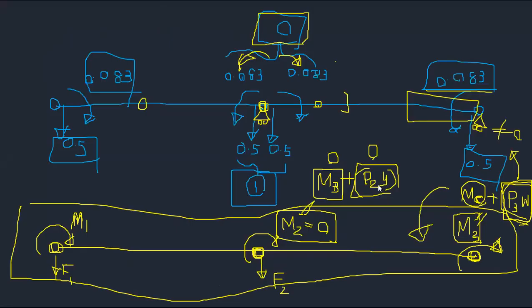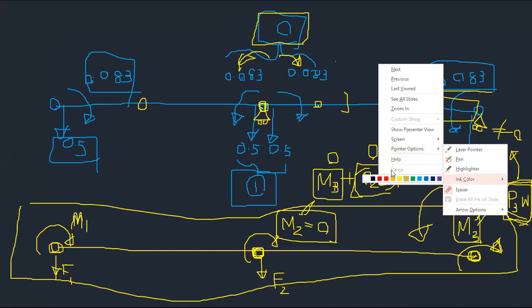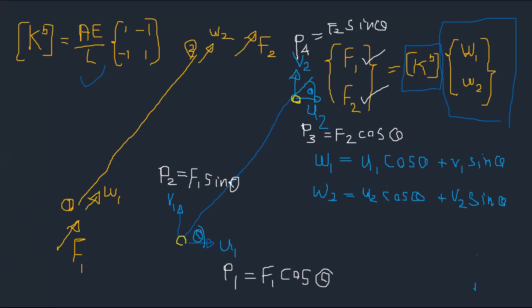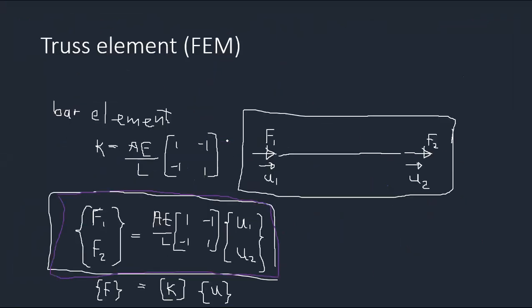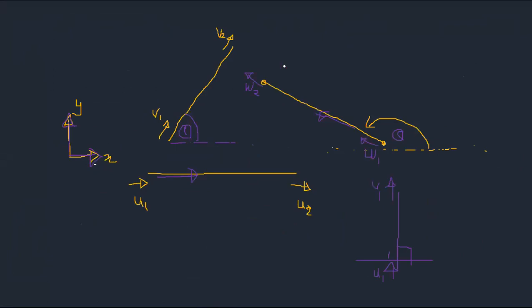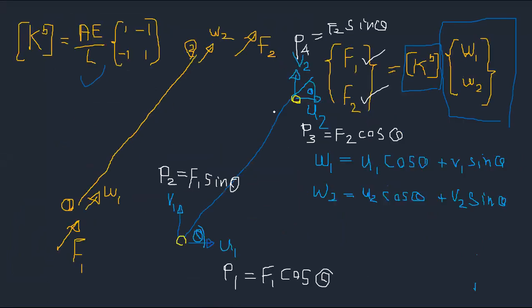So you can again go with this. What I was discussing was, a truss is a collection of bar elements. So you can't use the same matrix as it is, which was defined for a bar element along its longitudinal axis. So you need to take theta into account, right? So here's how you did it, right?